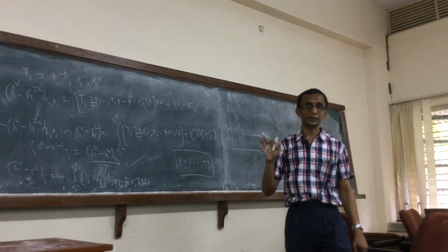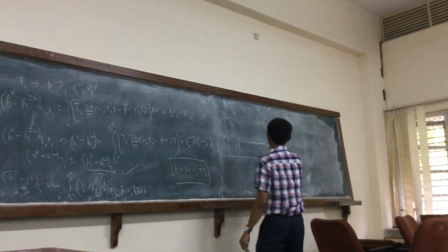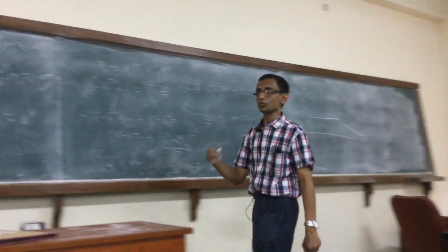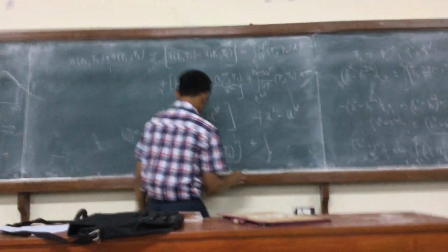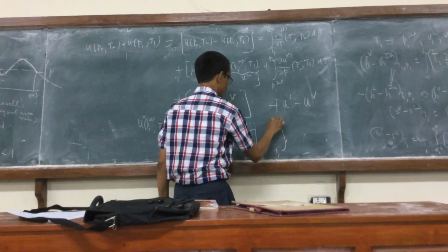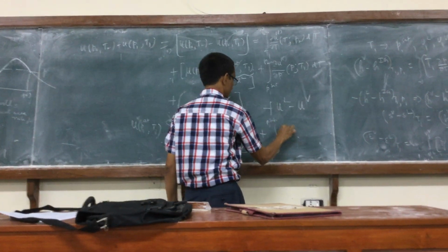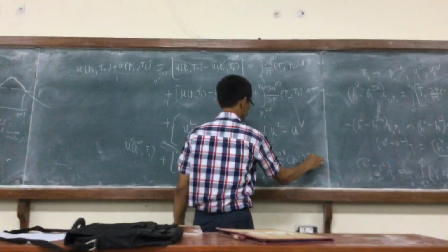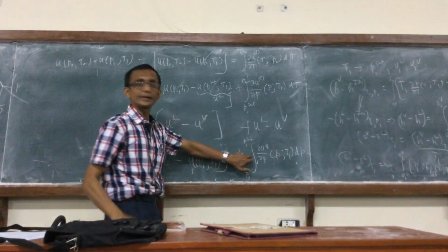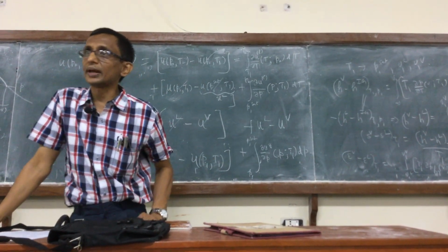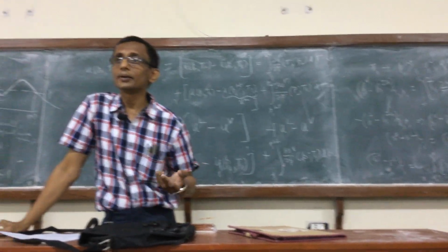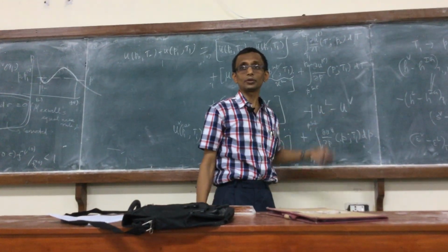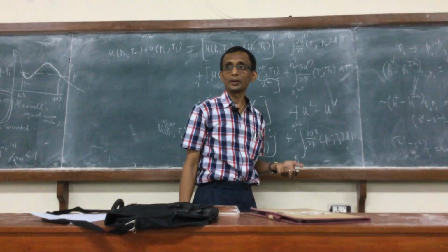It's important to know that that is UV, but it is at this point. So I am integrating from here to here. There is no discontinuity there, so I can directly use the derivative from P1 to P1 sat of dUg by dP at T1. Interestingly, you will see this is the only term for this part which is in the gas phase. So I don't really need even for this, because this can be directly obtained from the equation of state. I don't even need to know the departure function formula, right?